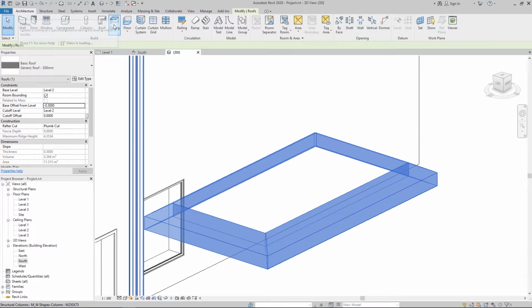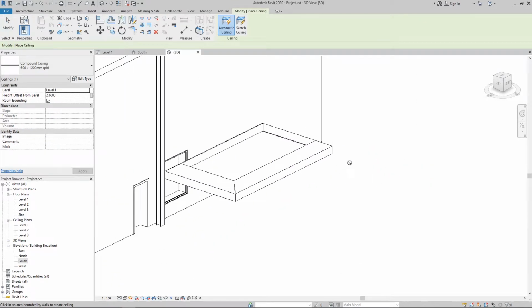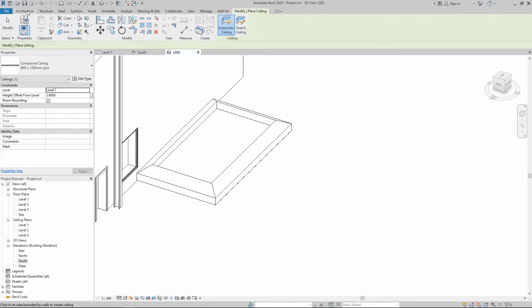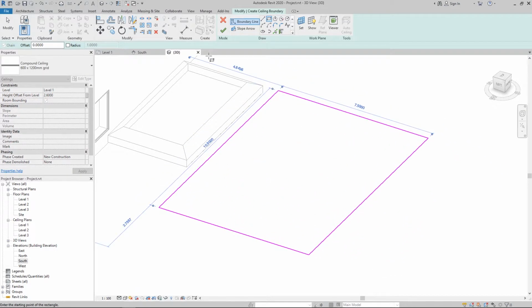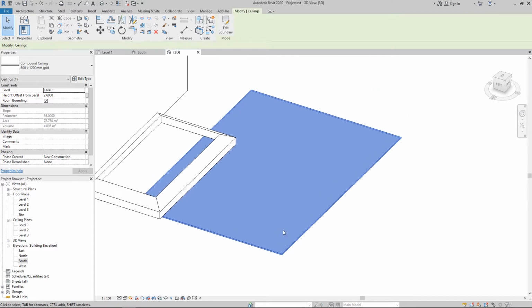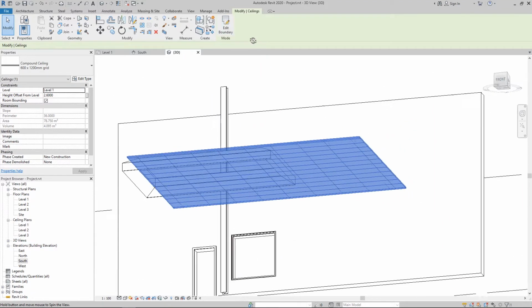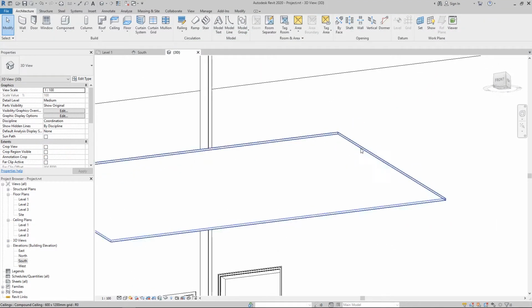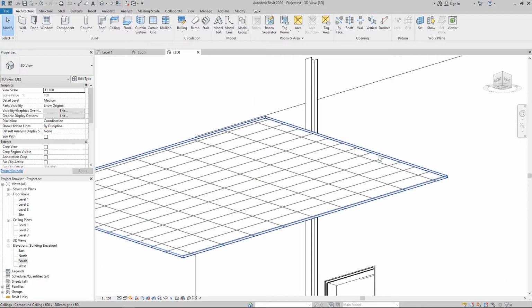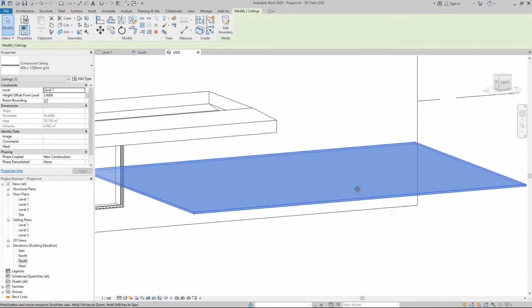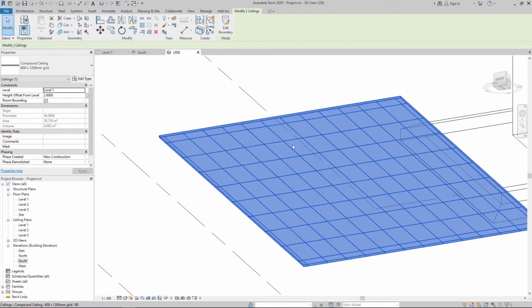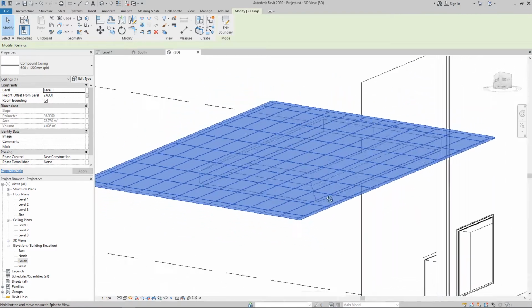Now I'm going to the ceiling. We can create it in the same way by clicking here in Sketch Ceiling and clicking here to create, let's say, this rectangle. Okay. So we can use this to hide all the systems that we may, like the ventilation systems or electrical systems that we are going to create in our project.